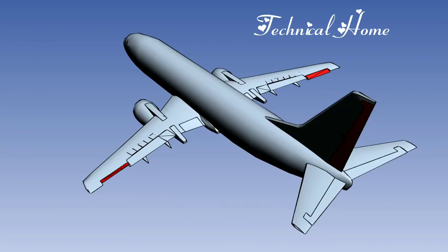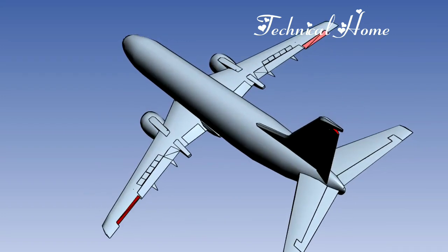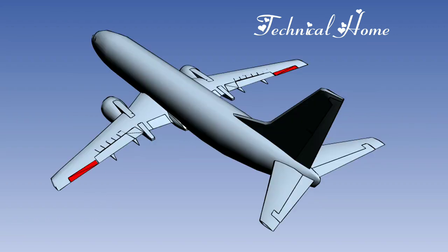In the aileron rudder coupling system, the aileron and rudder systems are interconnected, so that when the ailerons are deflected, the rudder automatically moves to counter the adverse yaw. The ailerons are normally situated at the wingtip, to give the greatest moment for the force produced. However, this also means that they cause the maximum twisting and bending loads on the wing. As the aircraft speed increases, this can cause a loss of effectiveness, or even reversal of the aileron. To reduce these effects, the ailerons can be mounted further inboard.